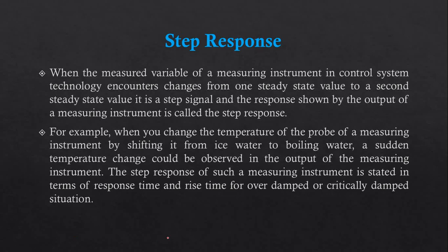So if we have over here our ice water and over here our boiling water temperature, it is going to be a sudden change like this, increasing very rapidly. So this type of change is called a step response. The step response of such a measuring instrument is stated in terms of response time and rise time for an over damped or critically damped situation.